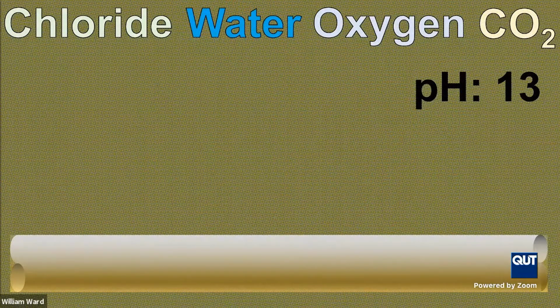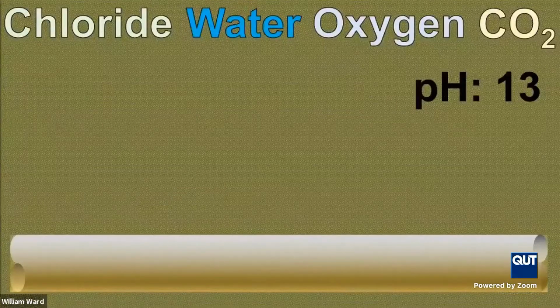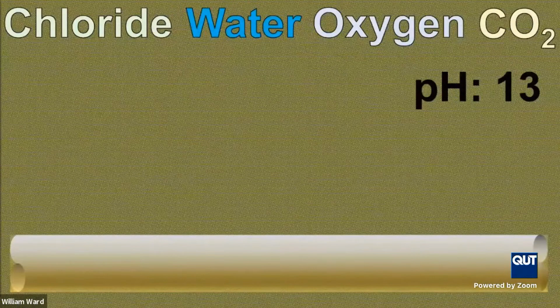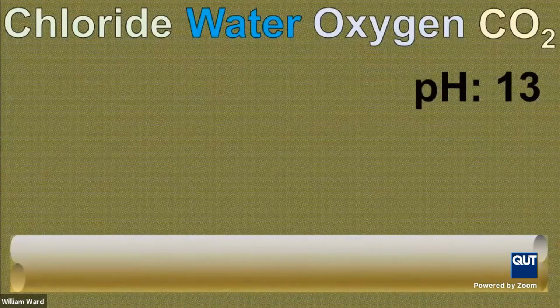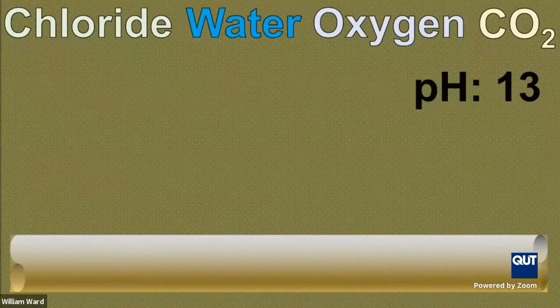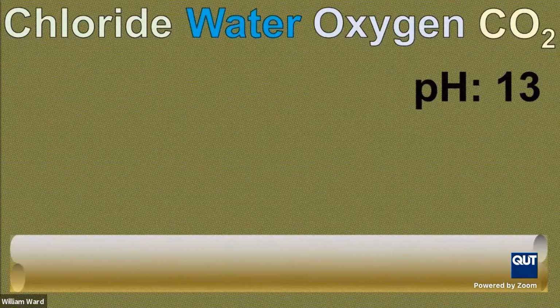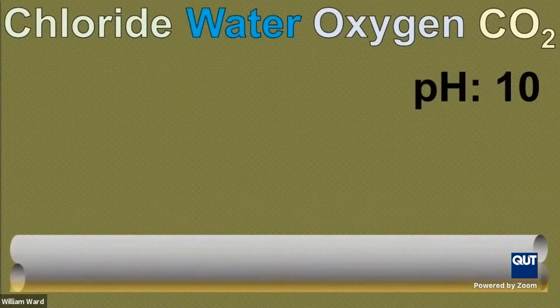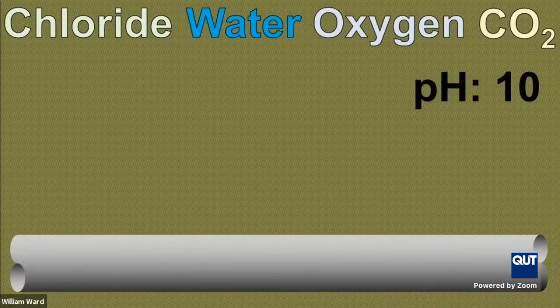Now, for my example, I'm going to be talking primarily about chloride ingress. So think a bridge or marine structure exposed to salt water. And the first protection of that structure is how long it takes for those chloride ions to diffuse from the surface to the level of the reinforcing steel. Then it will break down the protective oxide layer, lowering the pH, and our oxide layer will be stripped away, and it will promote what we'd call pitting corrosion.